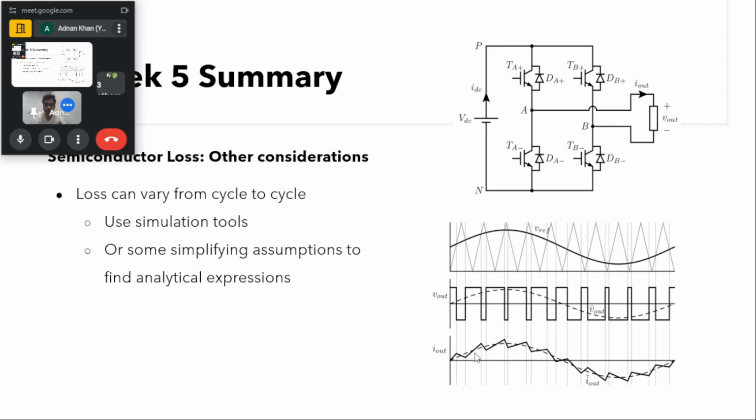Then we can see what the current is in a particular switching interval, and analytically calculate the switching losses at every instant by using software tools in MATLAB or some other mathematical tool, but it is a bit tedious process for these converters compared to the DC-DC converters.